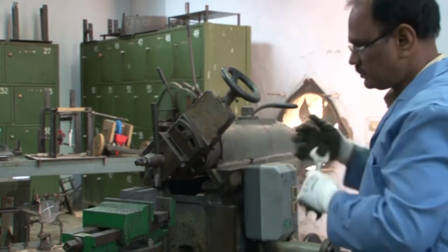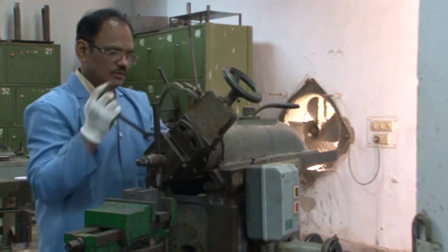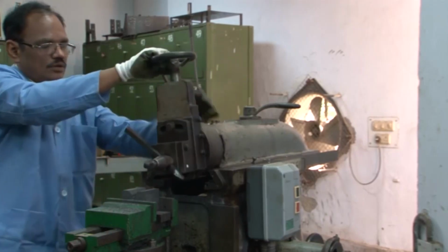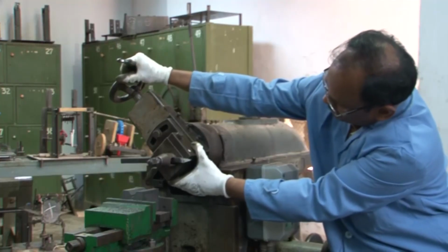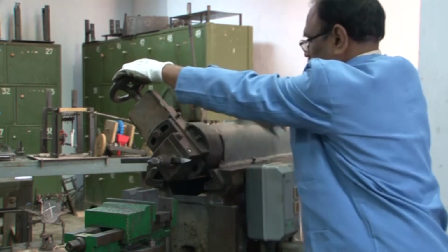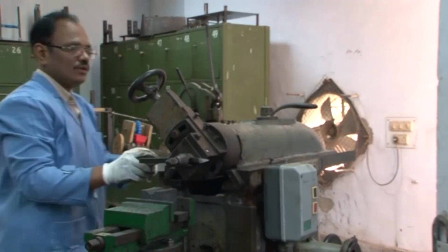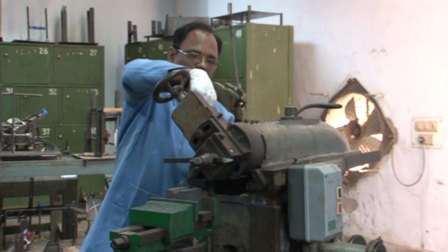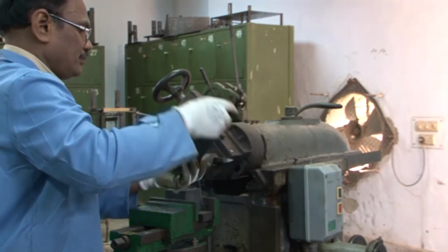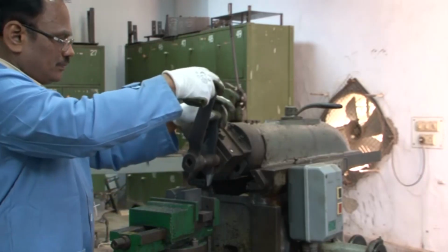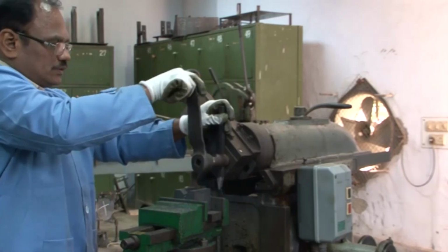So now the tool will be inclined to 45-degree on the other side, all right, so that the left side inclination can be done. Again, according to the graduation and the scale, circular scale there, the 45-degree angle is determined and it is fixed. After that, the tool has to be straightened up. Yeah, now the tool is being straightened up with respect to the workpiece, so that it could be perpendicular to the flat surface of the workpiece.